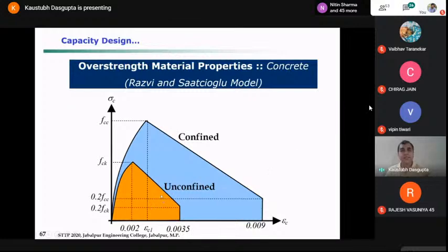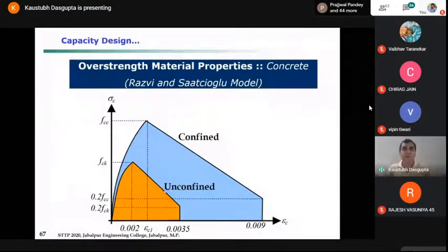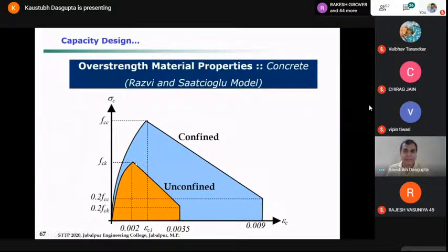So our design stress strain curve of IS 456-2000 is obtained directly from the cube test, and when you crush a concrete cube, there is no confinement, there is no reinforcement, right? So it matches closely with the unconfined concrete strain. So that's how you land up with very close values. What we see, only our IS 456-2000 stress strain curve doesn't rise to fck. It goes up to say 0.45 fck, and then it becomes flat. Anyway, that is idealized for design with the partial safety factor.